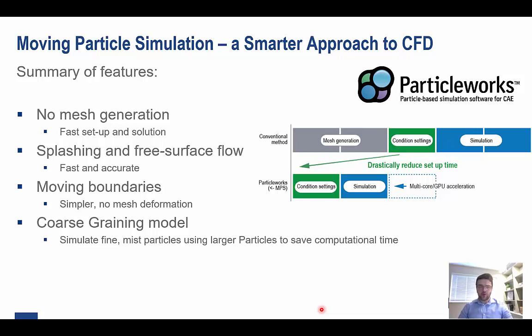Now, ParticleWorks is the only tool on the market that actually uses the MPS method. There are other particle-based CFD tools on the market. However, the MPS method is the only tool which was specifically designed for simulation of incompressible fluids such as water or oil. There are other tools on the market for particle-based simulation. However, these are not designed for simulating incompressible fluids, but instead compressible fluids, some of which have been adapted to work with incompressible fluids, but they're not their primary directive.